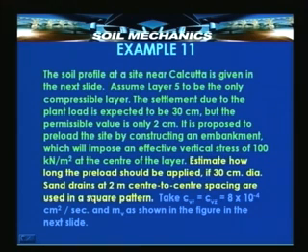and the other conditions are, sand drains are used, they are of 30 centimeters diameter and they are at 2 meters center to center, and the pattern of arrangement is given as square, although in the previous example we saw that triangular is a better option.